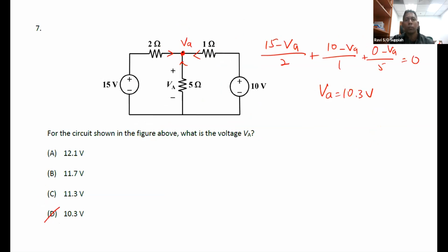There has to be one of the branches where the current is going out somewhere, correct? So it's the same thing. We do not know, and then we assume. We just come up with an assumption that all the currents are going in. So with that assumption, we know that at least one of them is wrong. Okay, we know that for sure. But we can still make the assumption because after we calculate the value, we will be able to know which assumption was right and which was wrong.